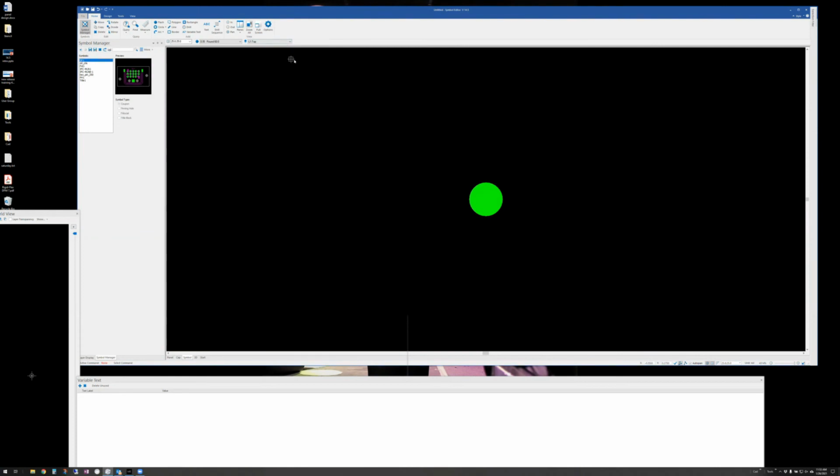And your symbols can go on any layer, and it's remembered. So if I wanted this to go on all of my layers, I could use the copy command and copy it off into different layers. Okay? And the layers here are not what you're used to seeing, because you generally will do this without a design loaded. This is generic layer names. So I want this dot to appear on the top, and if I want it on all layers, I would just check every layer, or maybe I just want it on the top and the bottom, so I just copy it over to the bottom layer.